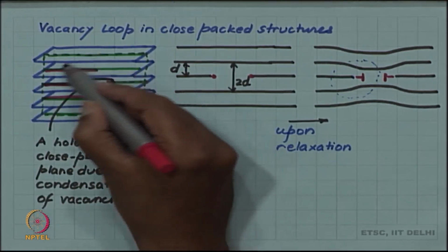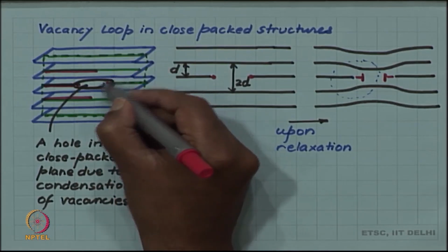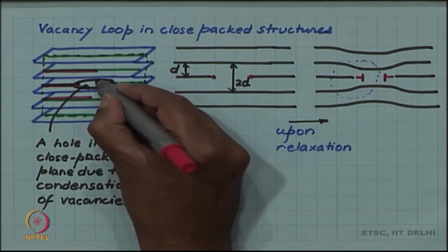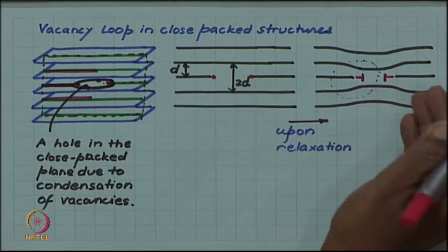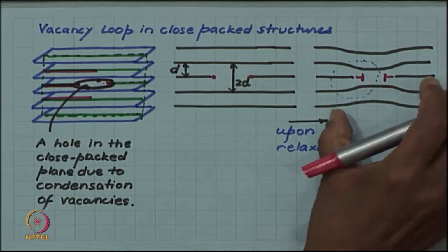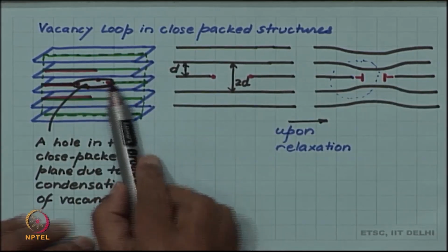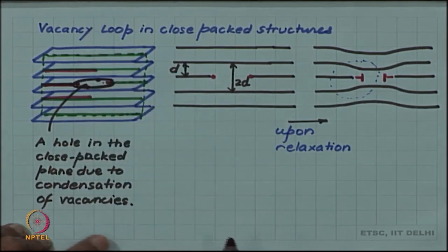You can imagine that if I cut this hole through other vertical planes, all the points can be shown as the dislocation line in a similar kind of picture, because the geometry of this loop is cylindrically symmetrical about this axis.